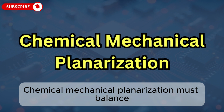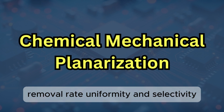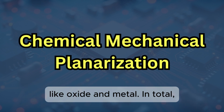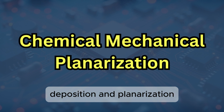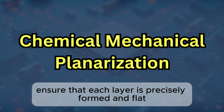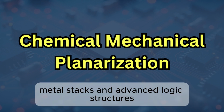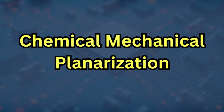Chemical-mechanical planarization must balance removal rate, uniformity, and selectivity, especially when transitioning between materials like oxide and metal. In total, deposition and planarization ensure that each layer is precisely formed and flat, creating the foundation for complex 3D integration, metal stacks, and advanced logic structures.